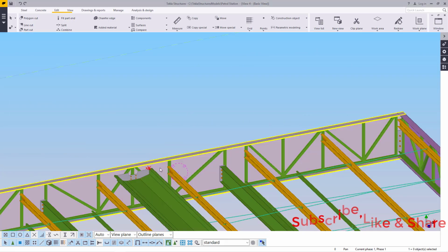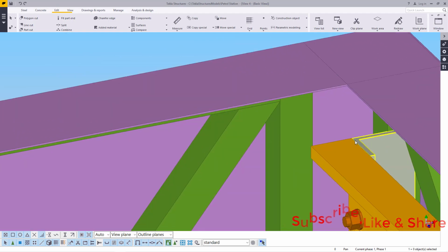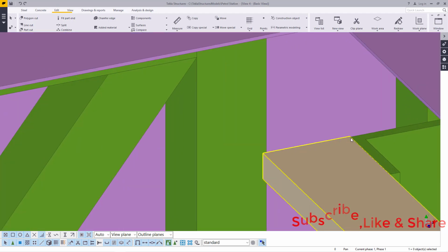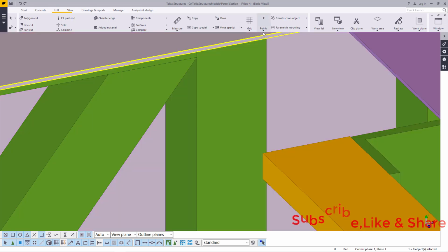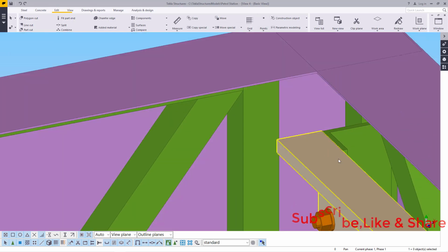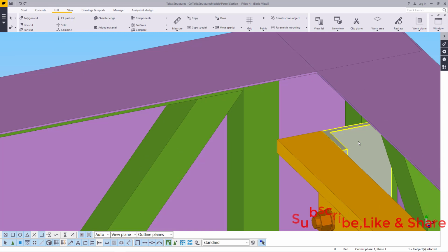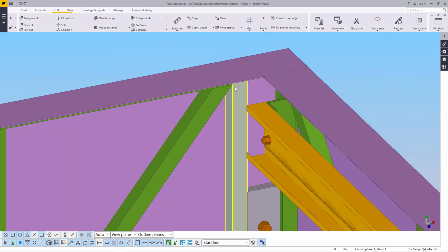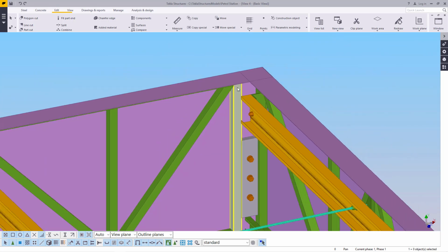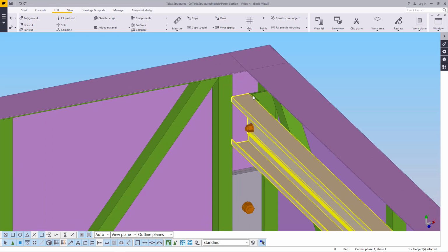And the same, I want to slightly change where my sheeting will start from, though this, as I told you, is only defined by the height of our cleats that varies from one to another. All the cleat heights are not the same. The reason is they are that way to define the slope of our purlins, which also defines the slope of our sheets.